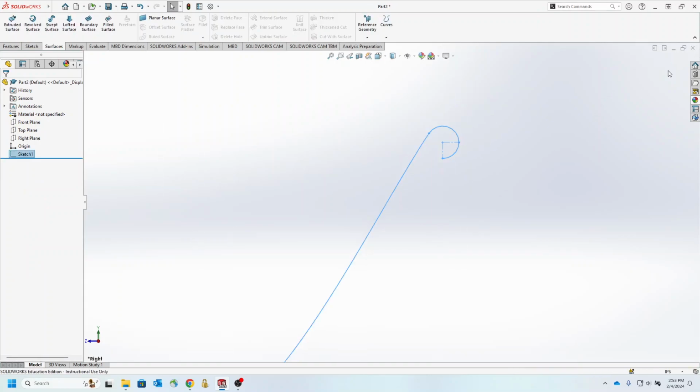So let's go back. If you go to the sketch, you see you have this shape. Now I want to create a profile for the shoehorn, like a semicircle at the end. In order to do that, I would like to create a plane here perpendicular to this curve and at this point.